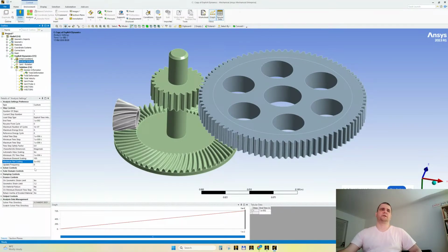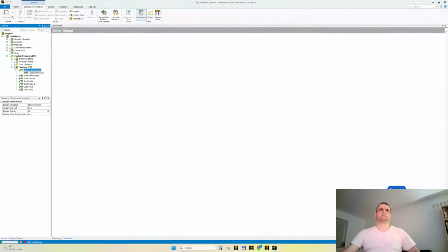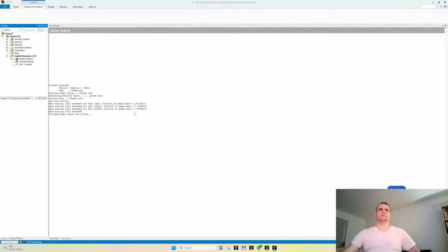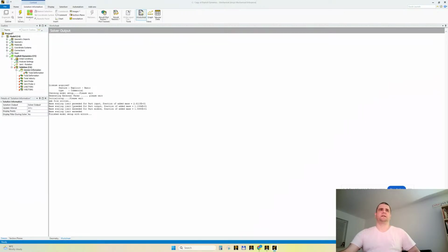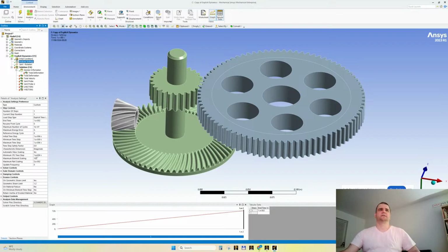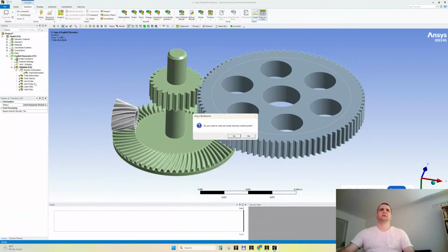So we will need to increase maximum part scaling, I think. Yes. So mass scaling limit exceeded for all 3 parts, 26, 11, and 16. The easiest way to solve this may be to assign 15. Does it work? Clear generated data, save, solve.